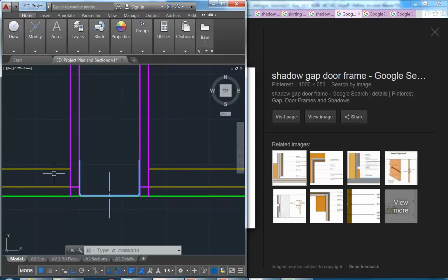Yeah, that's right. The floor lining would need to extend through to the stud framing. Because the bottom of the plasterboard is exposed, so that's visible above the floor lining. So you would need to bring this up and extend the floor lining across.